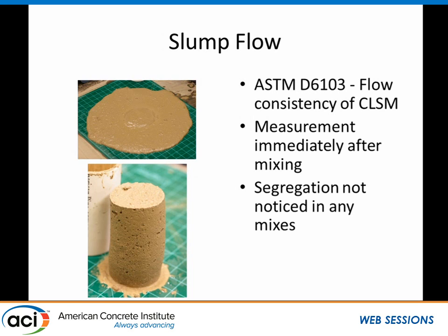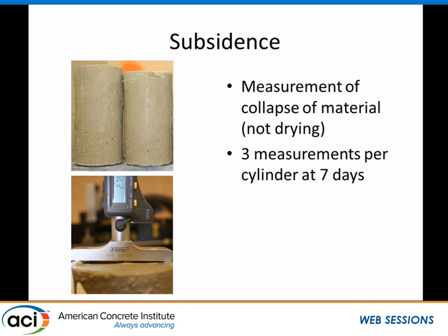Segregation, as a general rule, was not a big problem for these samples. We were pleased about that. That certainly is a big thing, that you don't want a big separation of your material when you're applying it. There's our slump flow. Subsidence was measured by